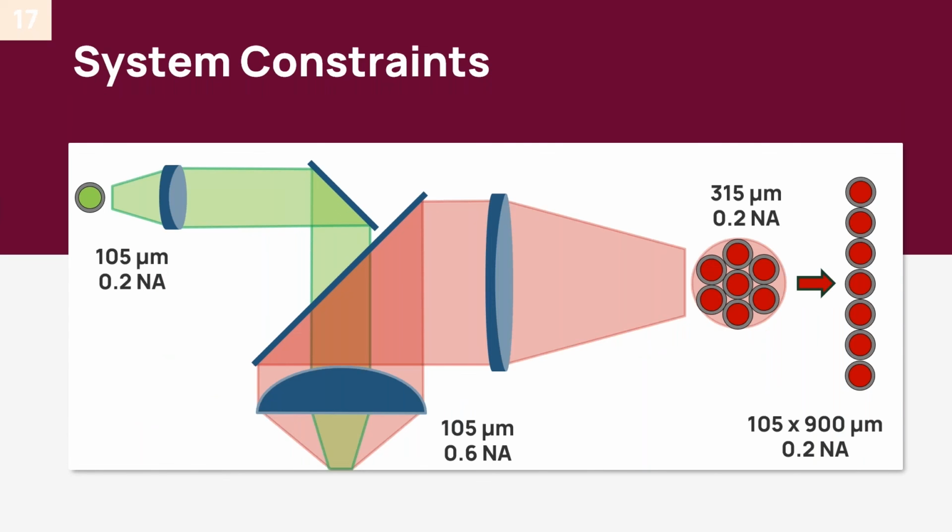And we made an example of this here where we look again at a 0.22 NA input fiber, 100 micron, green laser, and you send that through a lens condenser, an aspheric lens with a 3 times larger NA. If the focal lengths are the same, it's basically the diameter of the condenser lens that's larger than the diameter of the collimation lens for the excitation laser. So you end up with a spot size that still has a 0.22 NA, still 100 microns large, but now you can collect Raman signal from, in this instance, 0.6 NA, 3 times the size of the NA,